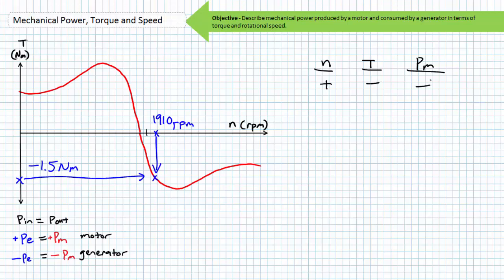If this device was hooked up such that the rotating magnetic field was rotating counterclockwise, and that same outside force also switched direction and started spinning the device at a speed above synchronous speed in the counterclockwise or negative direction, it would also have to overcome an opposition torque opposite to the direction of rotation. Negative rotational speed, positive torque, negative mechanical power. In both cases, positive rotation or negative rotation for a region above synchronous speed, torque exerted by a generator is opposite to the direction of rotation. Can you now dig regenerative braking on the same level that I do?